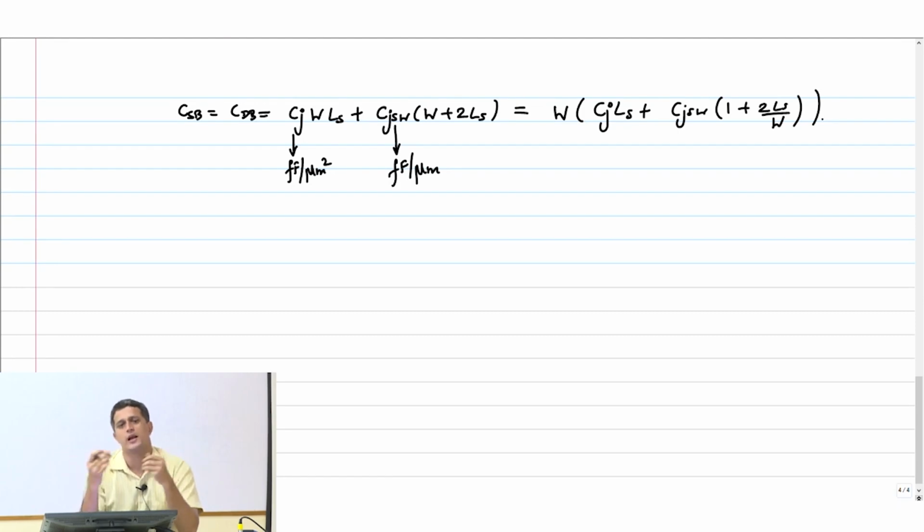So if you tell me that I will just make the size of the transistor much bigger, then be aware that you are going to actually load the previous guy significantly more. On the other hand, if you increase W, like we discussed in last class, the resistance drops. R equivalent is proportional to 1 over W. The resistance drops, there is no doubt about it. So this fight between resistance and capacitance is what is going to dominate your delay, and there is therefore going to be a sweet spot somewhere.